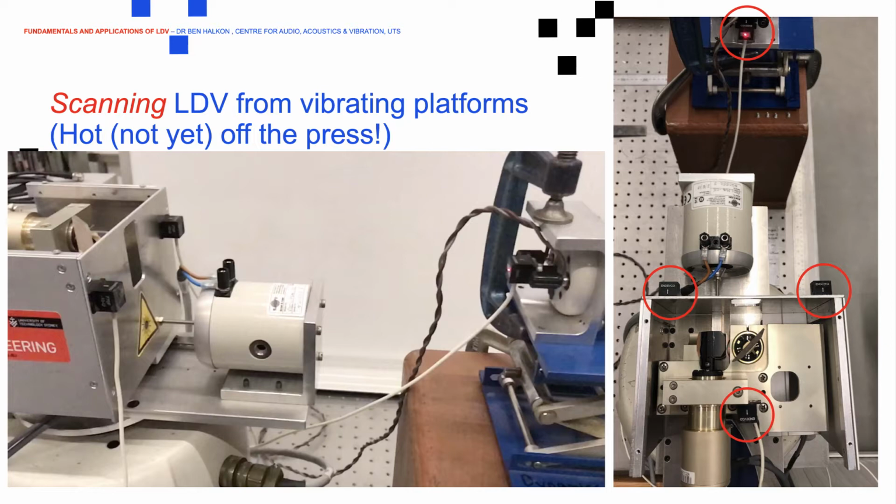But you can see from these plots, which look similar to previous plots, that before the measurement is corrected, we have a significant difference at low frequency in this case, because the vibrometer itself only really vibrates at low frequencies. Before and after, we get almost a couple of decades improvement, at least a decade improvement in the signal after we do that correction.